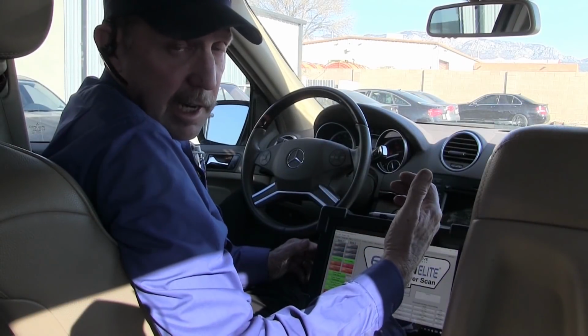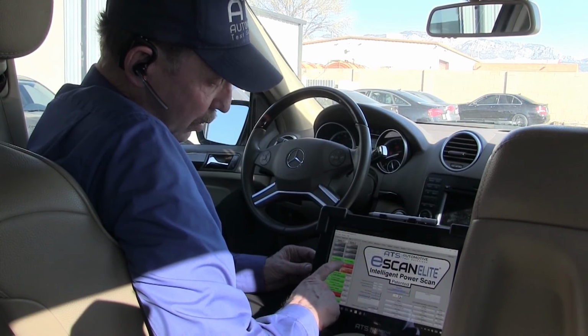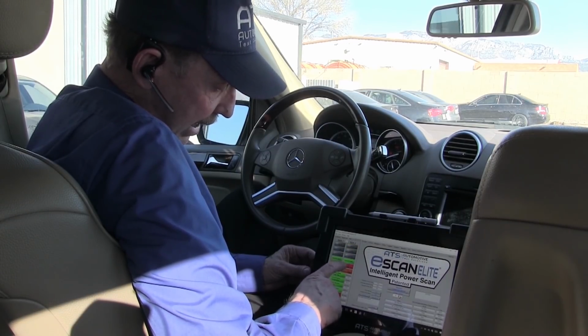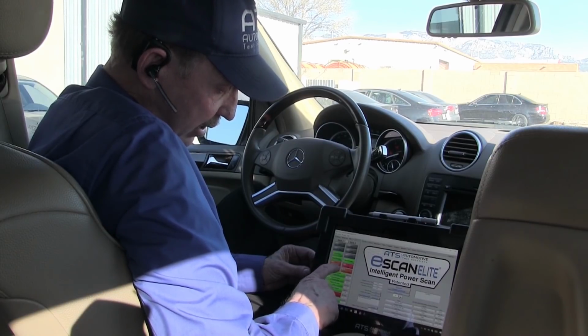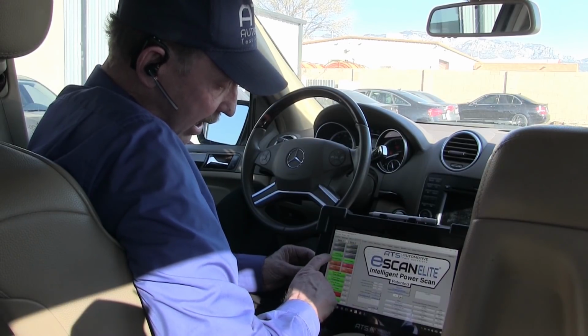Okay guys, I got the scan tool connected. Let's take a look at it. Right away I can see I have a big fuel trim problem at idle. Bank 1 is better than Bank 2. Bank 1 is orange and Bank 2 is red. This is long term and the bottom one down here is total trim. So we have a trim problem just sitting here idling.